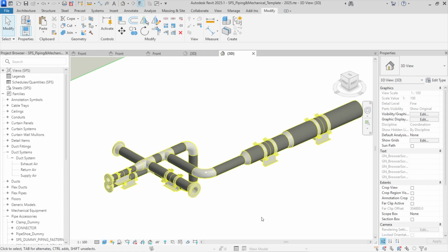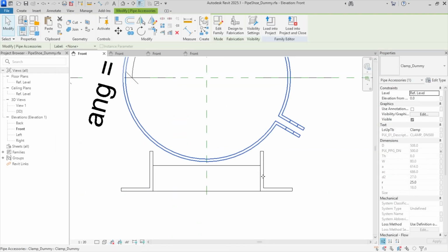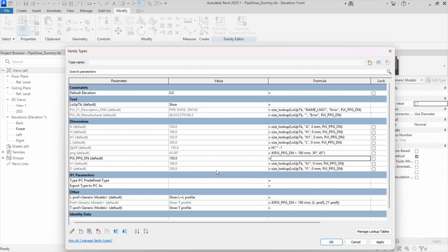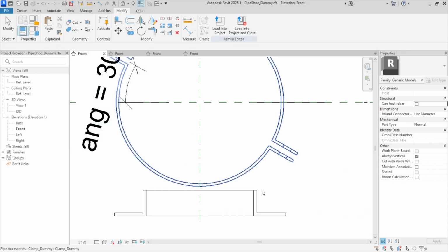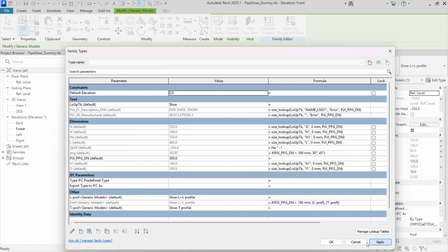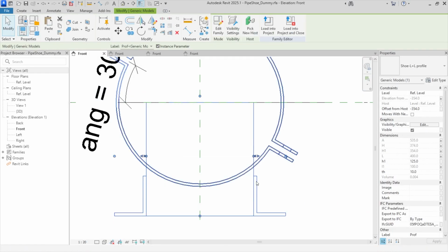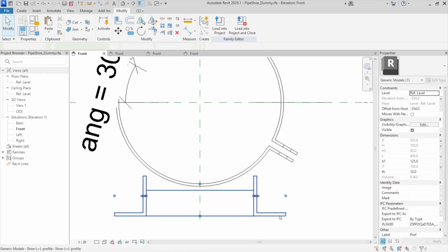And as I promised, here is a bug that I encountered during development of this family. You might run into the same issue as I did. When you're dealing with properties like family type, you need to make sure that both of the families have the same property names and also try to avoid using properties with names differing only in case.